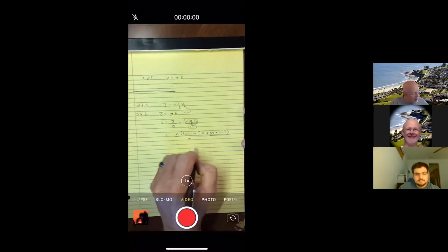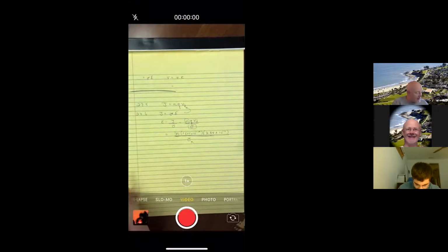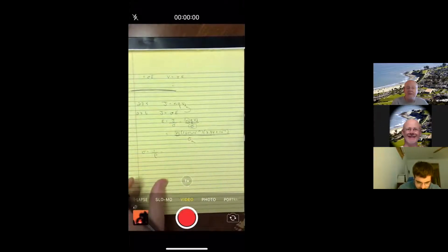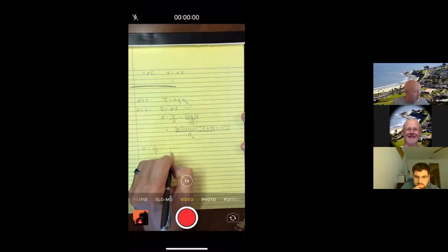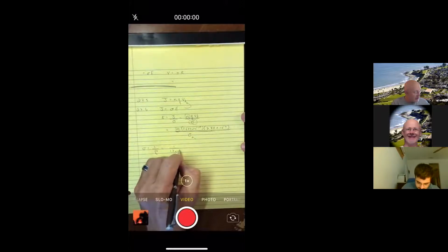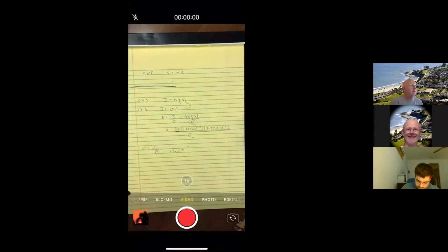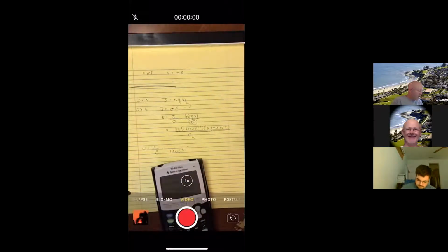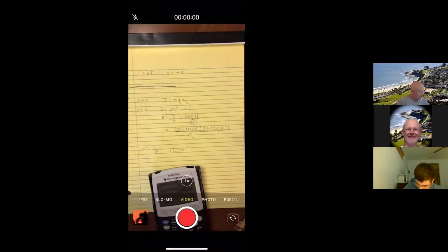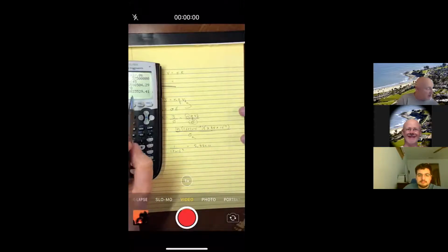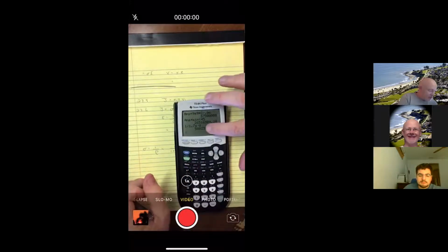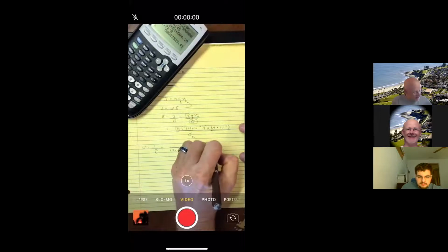So this number here, I guess, is what I'm going to do first before the harder one, n, and say, okay, this is the reciprocal of the resistivity. And the resistivity is given. And so this would be 1 over 1.7 times 10 to the negative 8 for copper. And so that's just right out of the table. So 1 divided by 1.7 times 10 to the negative 8 comes out to be 5.88 times 10 to the 7.